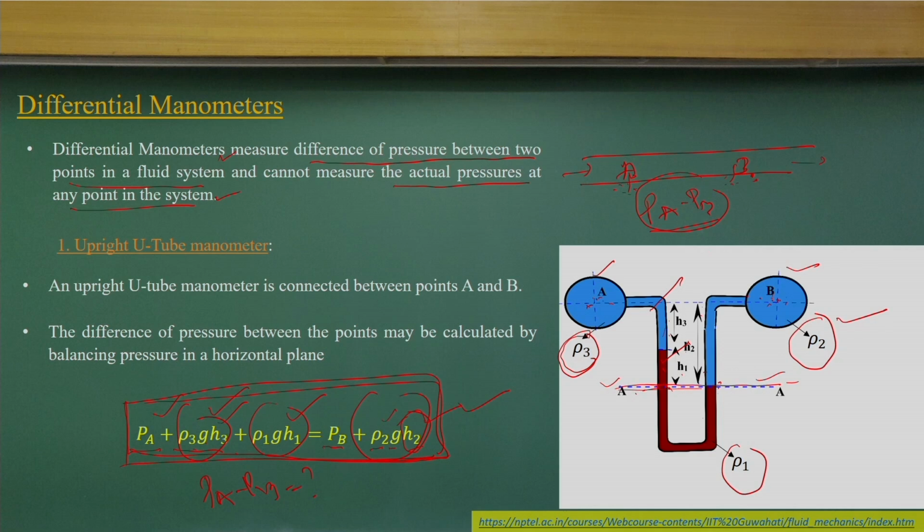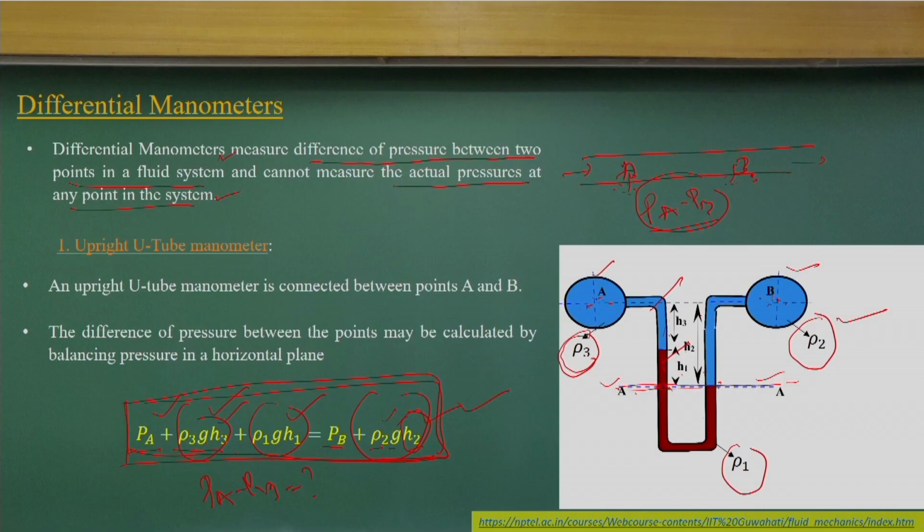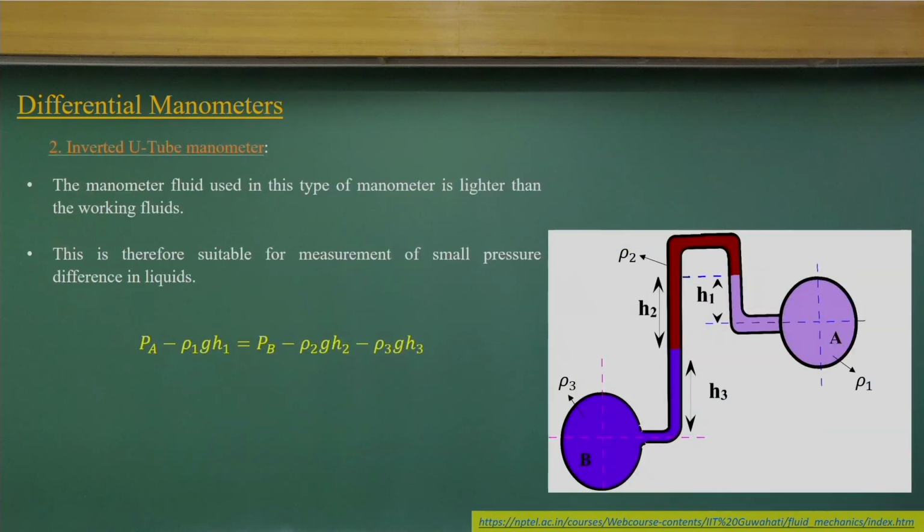So, whenever you get a manometric application problem, first you choose the appropriate surface where you can write the pressure equations. If you know that, then you can solve these problems easily. It is not that difficult.